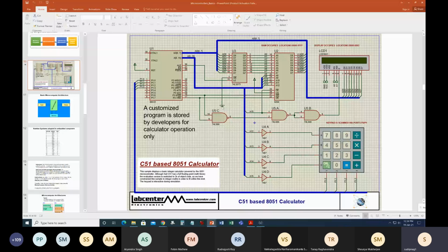And AD, basically you take the data part of it and then connect it to whatever peripheral or RAM chip you have. You can share the data bus among multiple peripherals or memories, because any one of these memory or input output devices will transfer data through the data bus. And then you have connected chip enable bar through some logic signal like A15. You have to configure this through the program, then only this will work.